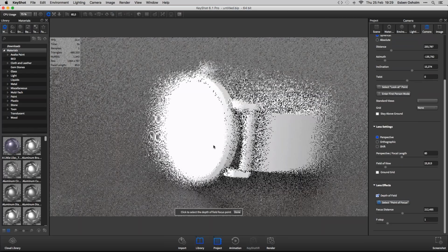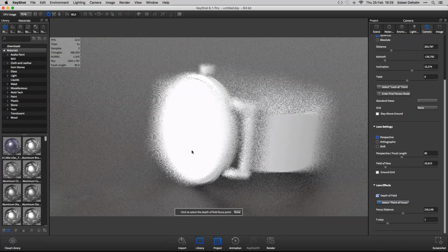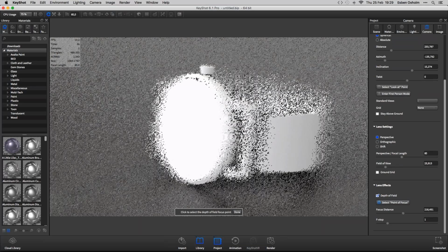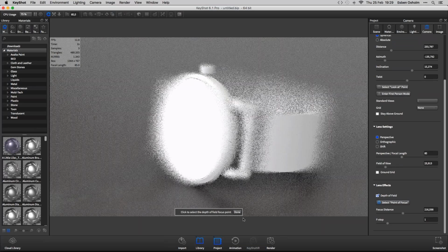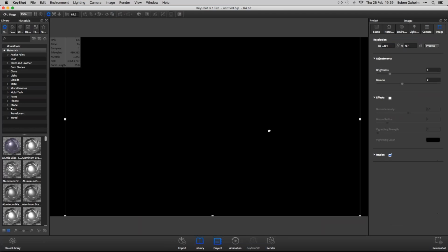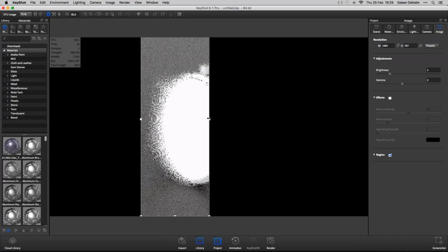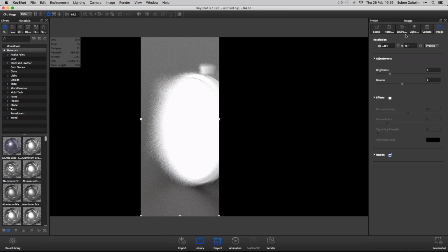Again, I know I want this area to be the one in focus. And I can see that the f-stop is way too small. But I just want to turn on the region rendering first, because it really helps things to res up way quicker, and it's easier to assess the settings.